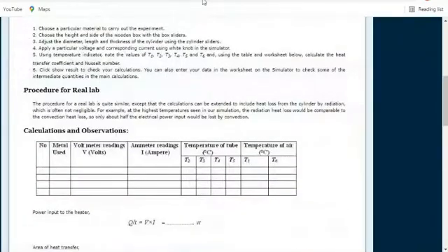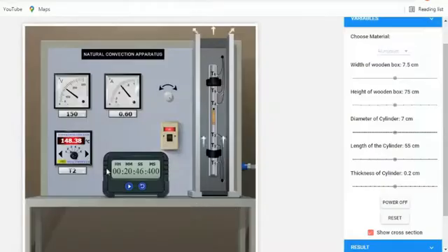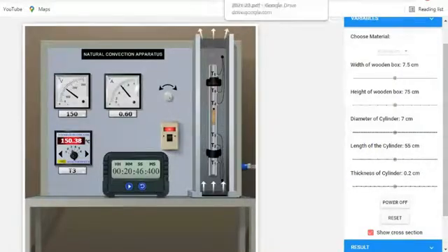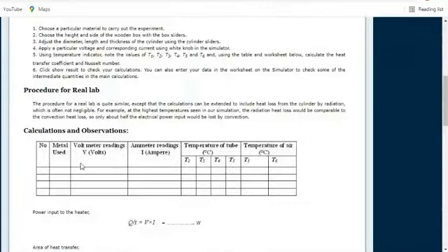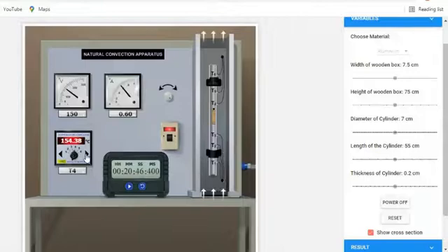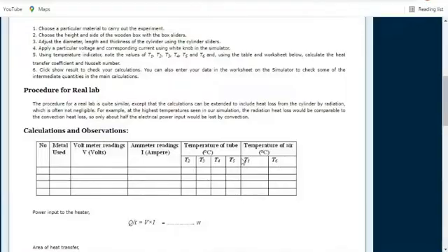Note down here, in this block. Then click on here for T3, and again you can note it here. So aluminum is here, voltage we kept is 150, current showing is 0.64, and then we measure the T2, T3, T4, T5 temperatures of the tube, and then we can measure again with the help of this knob by changing the knob position. You see the T6 36, T5 156, like this. Everything you keep here.